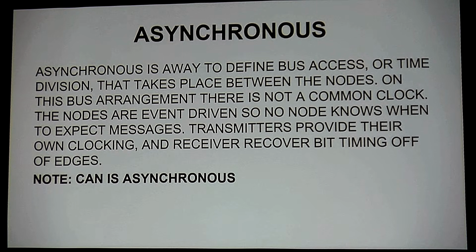Each module has its own clock. That means each module has to keep his own time. Now, because he has to keep his own time, guys, this starts to become one thing you need to really understand, and we're going to get into this. This is where a lot of your communication problems come from. The quartz clocks in each one of these units are different, and they're not all exactly timed correctly. I get 40 modules on a bus. I got 40 different clocks, gentlemen. 40 different clocks that are going down to microseconds to communicate. And if you miss a microsecond, you miss your communications. Temperature, age, all kinds of things start to change the clocks between these processors. Now the processors can't keep time. And I'm going to explain exactly what happens when they don't keep time. But that's what we're dealing with within a CAN system.